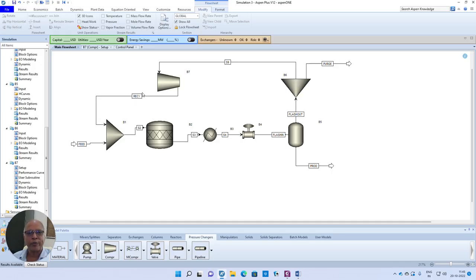How many components do you expect? All the 3 will be present. So at least you are required to guess 5 values. So temperature, pressure, composition, whatever those 5 variables are. Normally, Aspen makes these initial guesses for any recycle stream or tear stream: the component flow rates are presumed to be 0, so the C variables are taken care of, and the pressure is assumed to be 1 bar, and the molar enthalpy is taken to be 0. So these are the 5 guesses Aspen normally makes, right?